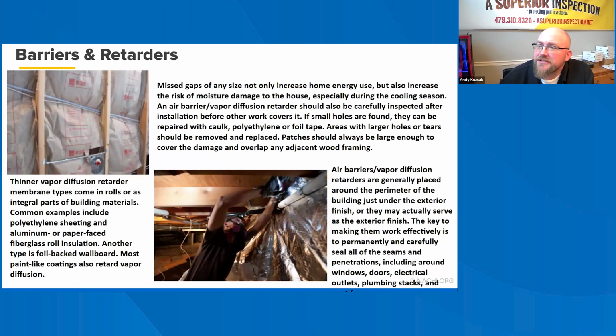All appropriate surfaces should be covered, or moist air within the cavity may condense, which could lead to dampened insulation. The thermal resistance of wet insulation is dramatically decreased, and prolonged wet conditions will encourage mold growth and wood rot. An air barrier vapor diffusion retarder attempts to accomplish water vapor diffusion and air movement control with one material. This type of material is most appropriate for southern climates, where keeping humid outdoor air from entering the building cavities is critical during the cooling season.